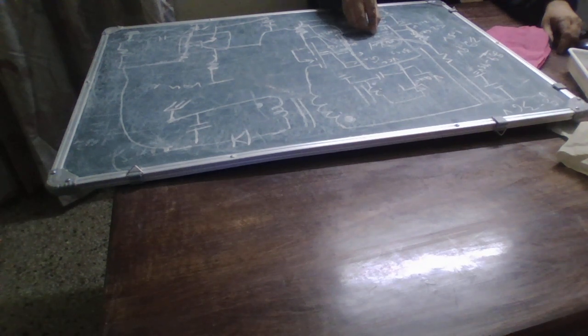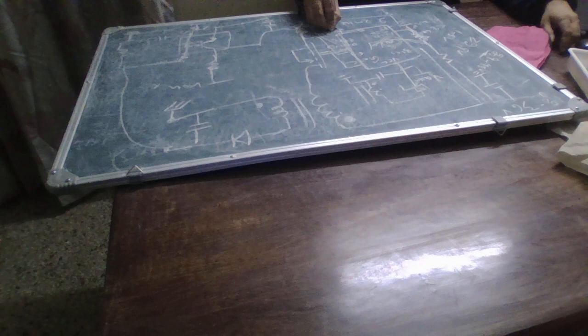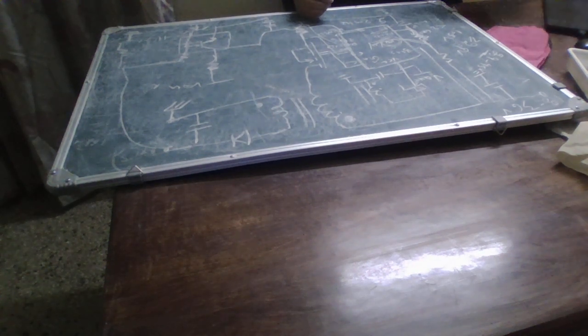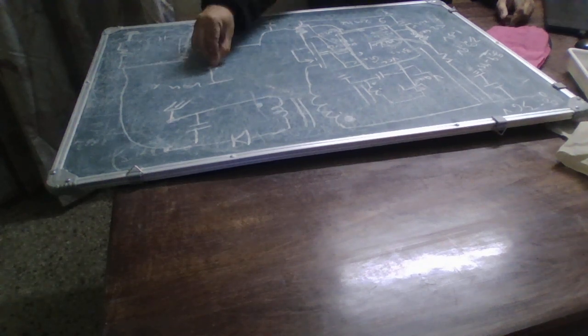So this is the analog ground, AGND. We can connect it to the analog ground plane through a wide and short path. We have a COMP pin, that's basically the output of the internal transconductance error amplifier. The COMP pin is for the loop compensation components, connected through this compensation pin. Between the pin and the ground, you have seen that I have connected C and R, optocoupler, auxiliary.